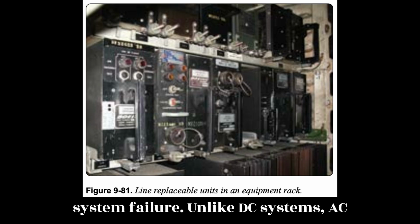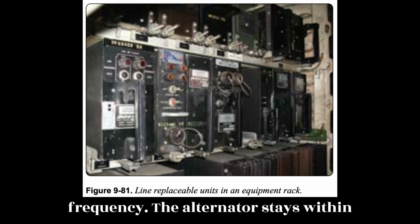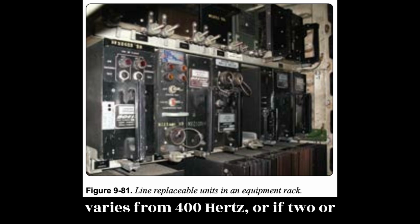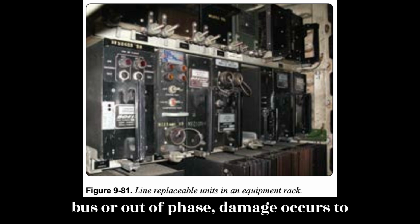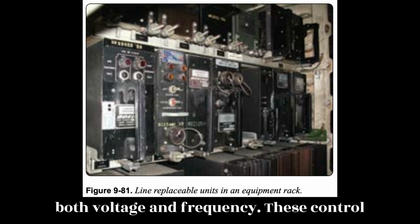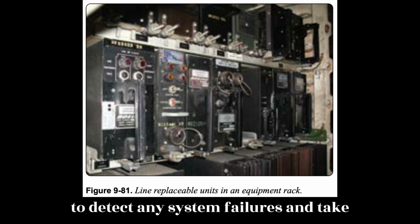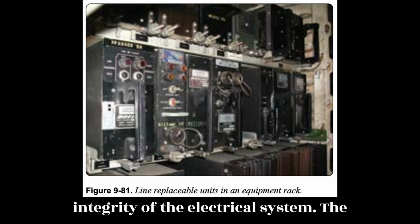Unlike DC systems, AC systems must ensure that the output frequency of the alternator stays within limits. If the frequency of an alternator varies from 400 Hz, or if two or more alternators connected to the same bus are out of phase, damage occurs to the system. All AC alternator control units contain circuitry that regulates both voltage and frequency. These control units also monitor a variety of factors to detect any system failures and take protective measures to ensure the integrity of the electrical system.